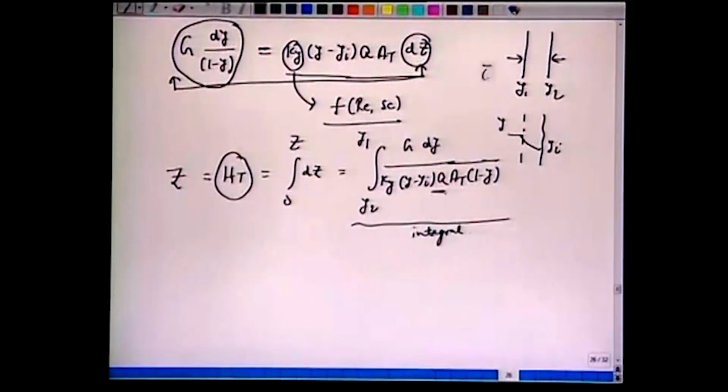Area, superficial or this interfacial area, already we have discussed. This comes from the supplier, the manufacturer of the packing, meter square per cubic meter, is known to us. The cross sectional area, meter square, this comes from hydrodynamics very often. Pressure drop considerations which we have discussed earlier, this is nothing but G over G prime, that gives us cross sectional area, from where we get this At.